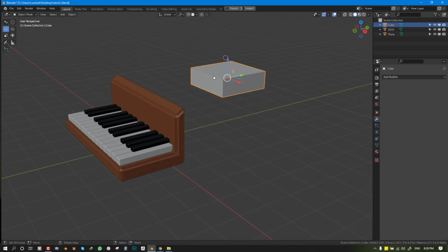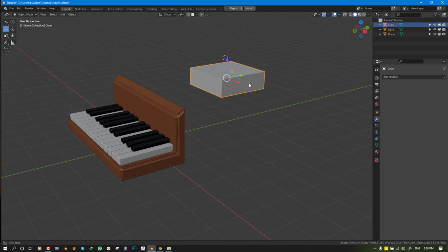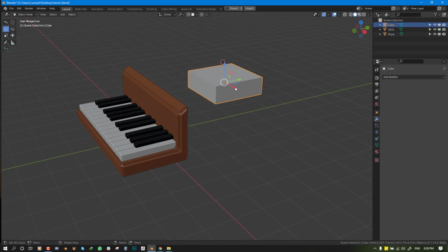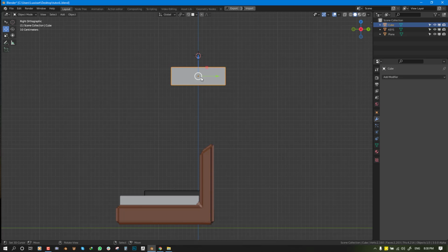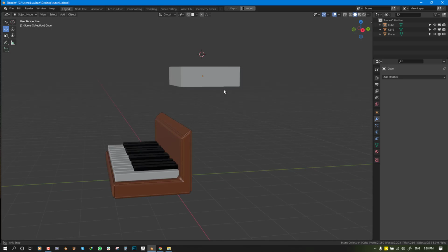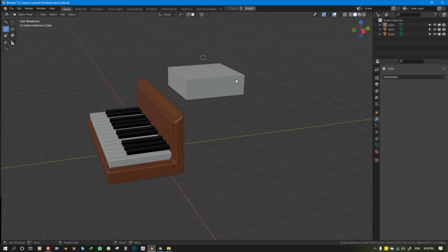And we want it to be based on proximity, so only when the object comes close to it can we see that effect. The basic way we want to do it is using a combination of armature, and since Blender armatures don't really have a way to use proximity to trigger stuff, if it exists I don't know, we'll start by adding the armature.